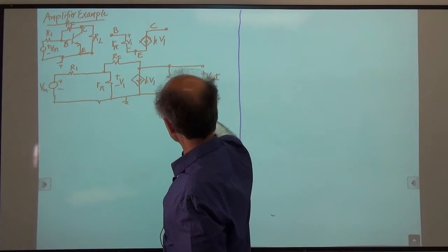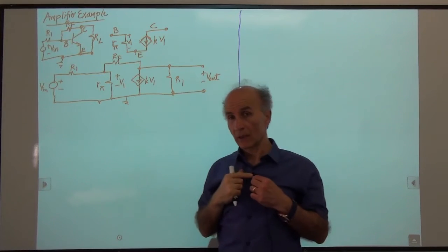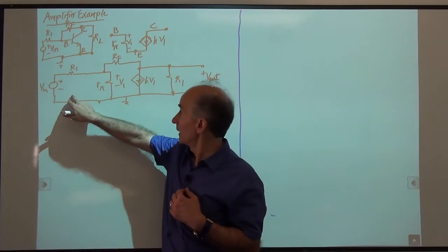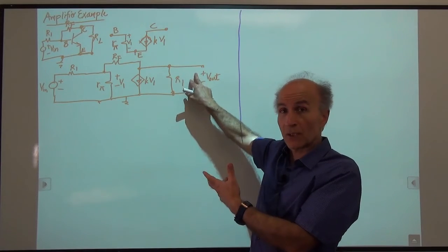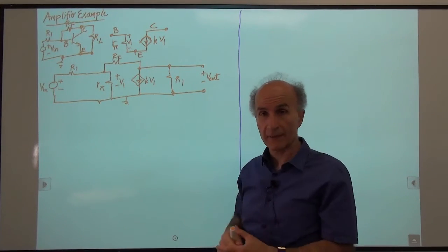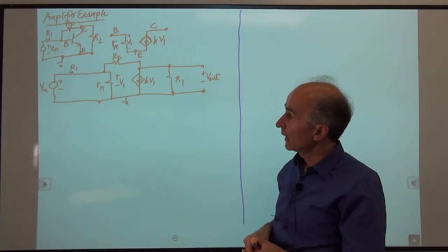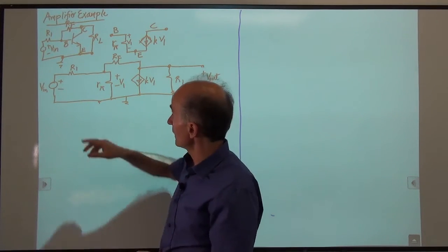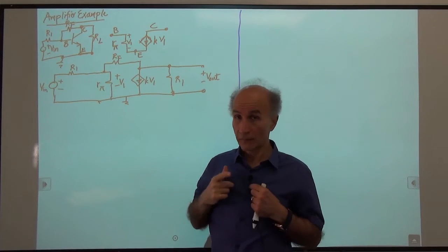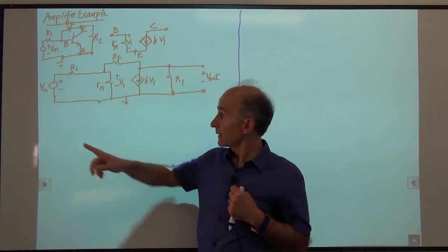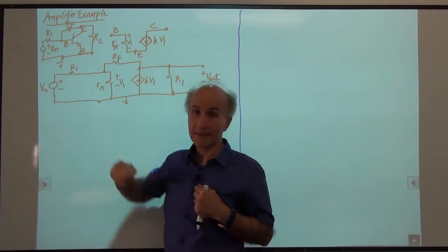So what has really happened is that my microphone signal, which is coming from here, is applied to this amplifier. It generates presumably a larger voltage, and that voltage goes further for processing, right? By the way, if you're curious where this R1 comes from, the Thevenin equivalent of the microphone itself is something like this, a voltage source and a resistance.